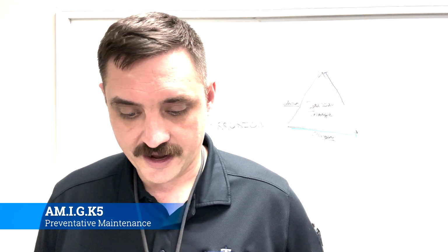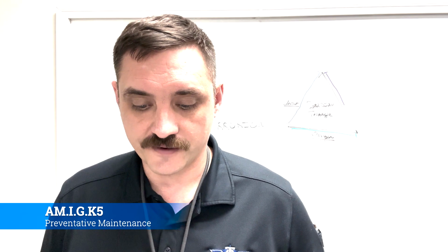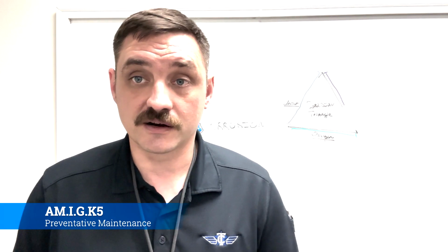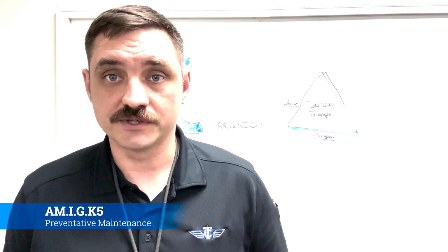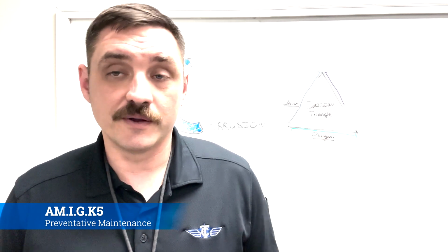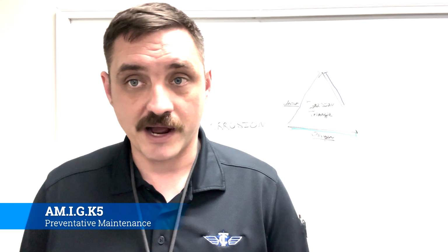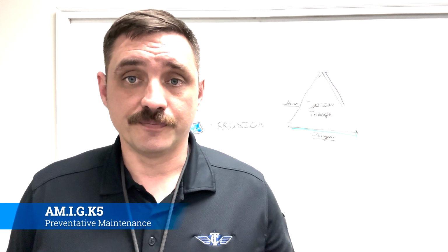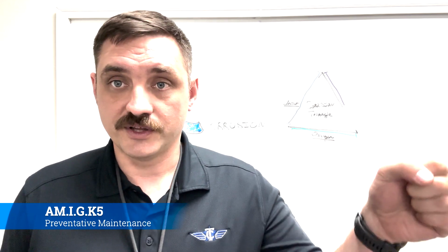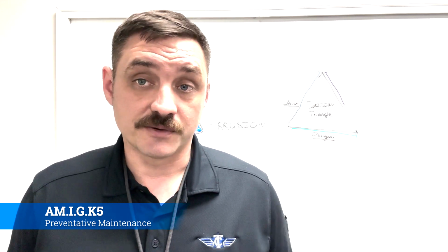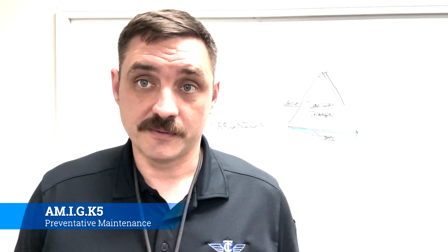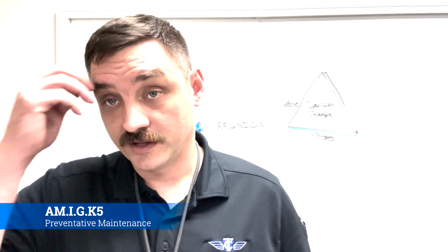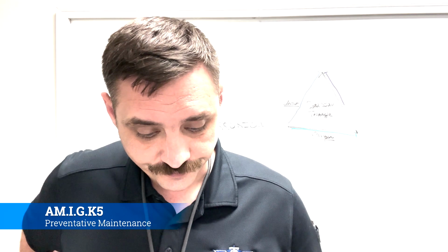Number 9, daily draining of fuel cell sumps. You'll be required to sump aircraft fuel cells. We have a flight going and we have a bunch of Cessna 172s or Piper Cherokees or Archers or whatever the scenario is. Go underneath them and you'll sump the fuel tanks. When you sump those fuel tanks, all the water and trash will come out. By getting that water and trash out, you're preventing corrosion and a list of other issues as well.